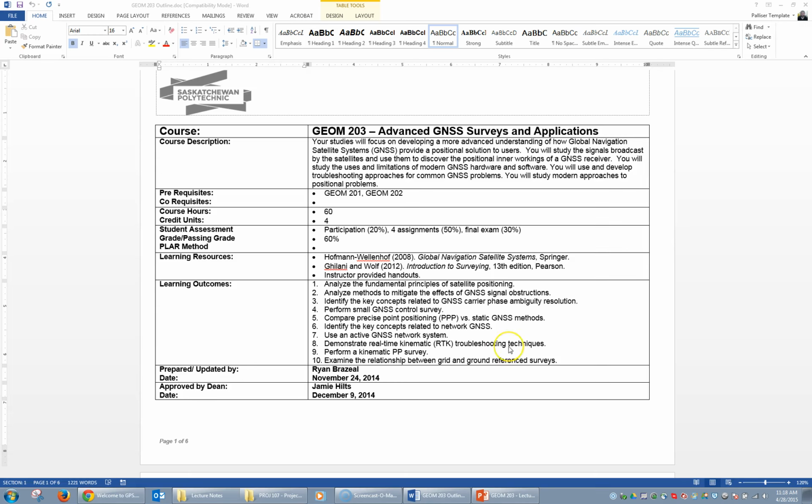The troubleshooting techniques obviously depend on the equipment that you're using, so we're going to keep this fairly generalized, so we understand largely what the configuration settings are. And the configuration settings are going to be fairly common terms, say like RTK format or correction format, for example. So if you see those terms, you understand what they mean. And by having that knowledge, you'll be able to troubleshoot communication and configuration problems with theoretically any GNSS equipment.